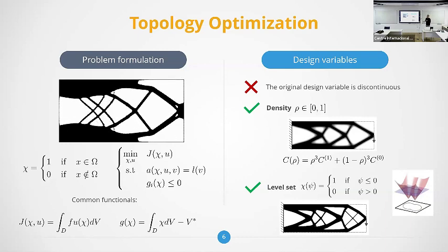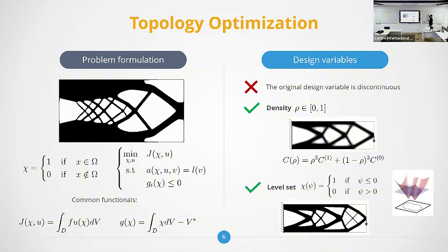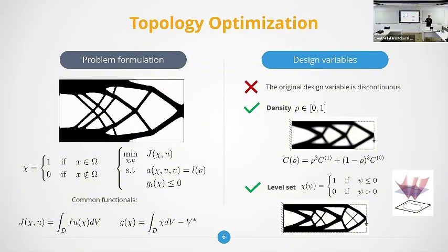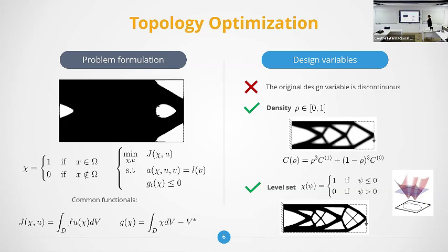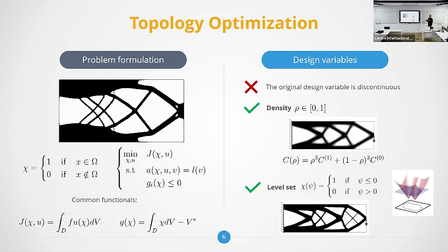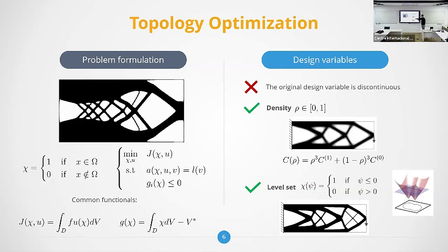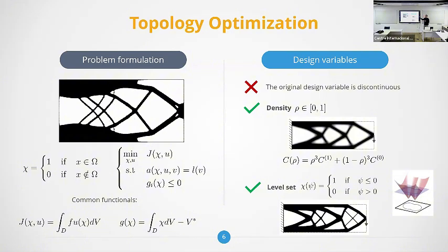In topological optimization, we usually find, for instance, density, which is basically the continuous version of it, with the appearance of gray areas in the interfaces between black and white regions. Then we have to think about the need to interpolate the elastic properties in these gray areas. We have to characterize them. It can be understood as some sort of composite material. And one way to interpolate this elastic tensor is by using the SIMP method, which is this expression here.